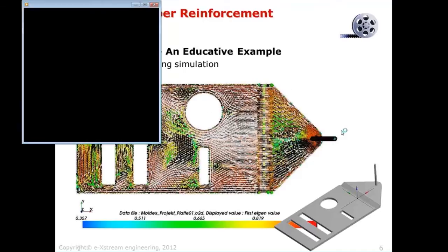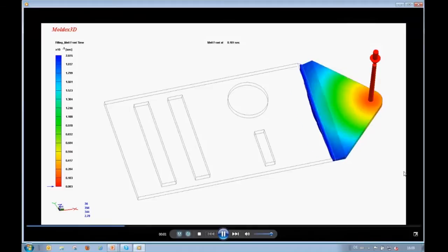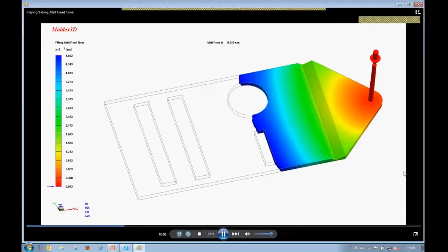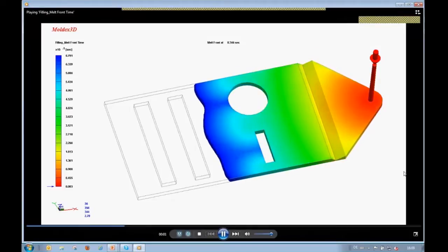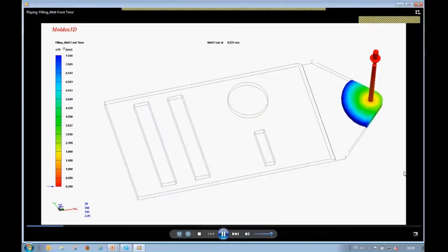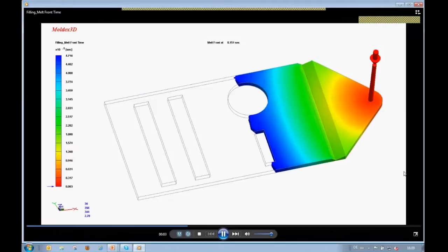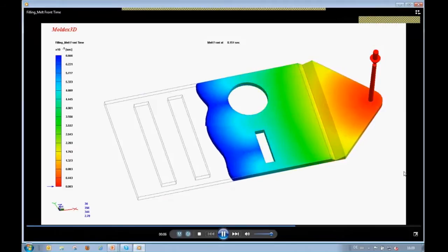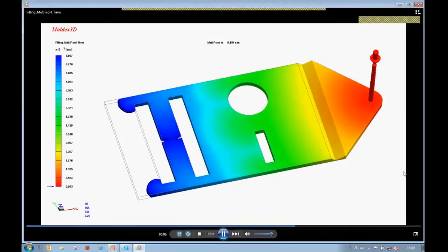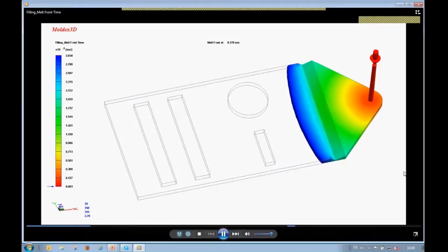So let's just take a look at the injection molding simulation, the filling simulation itself. And you can see that in this plate we have reduced quite a complex situation of a three-dimensional part to two dimensions. So the plate is filled with the melt, and then we have introduced some nice holes into the plate to enforce what we would call a flow line after the holes.